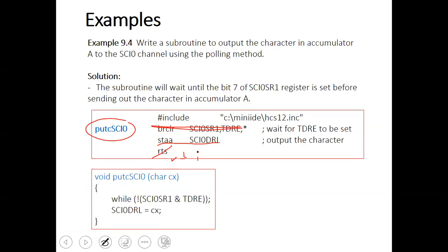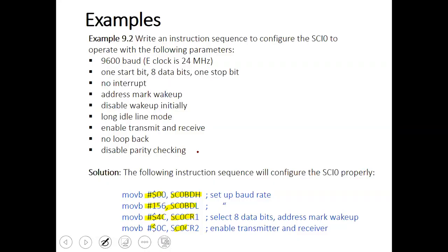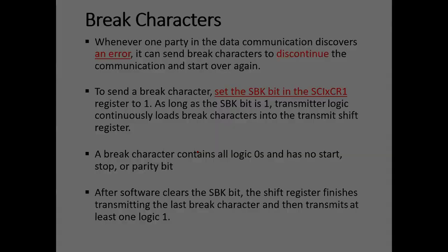What else? We need to clear the flag. Yes, we need to clear the transmitter interrupt flag. And how can we clear the interrupt flag in this microcontroller? By simply writing 1 to the flag. And this is shown or written here.